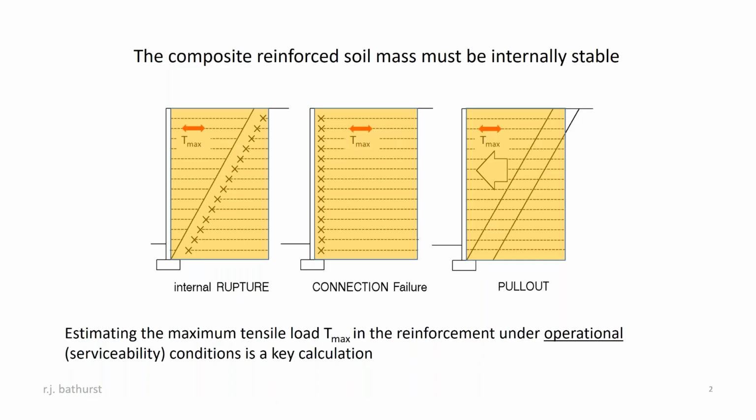In order to do that, one of the primary calculations, and indeed the key calculation, is to calculate the maximum tensile load in a reinforcement layer under operational or serviceability conditions.